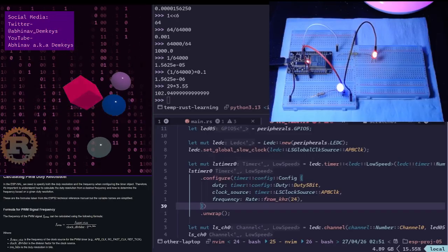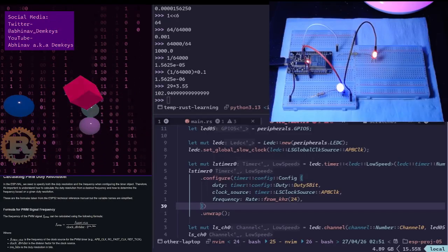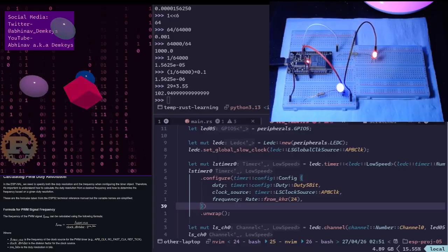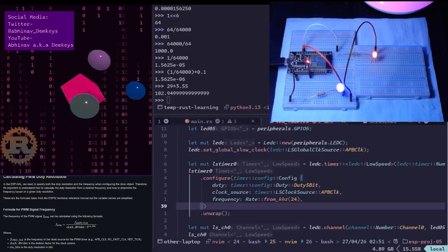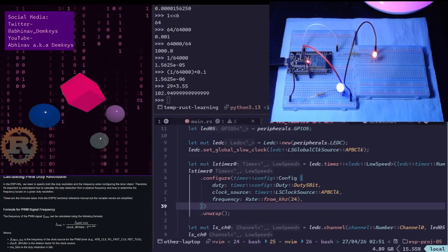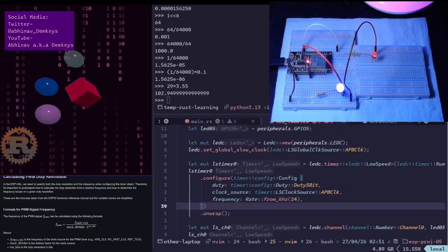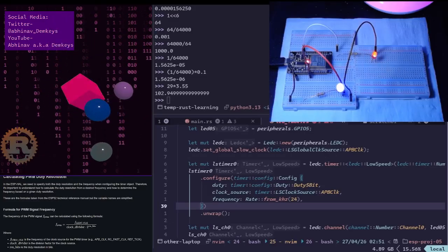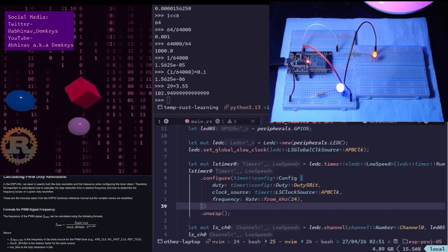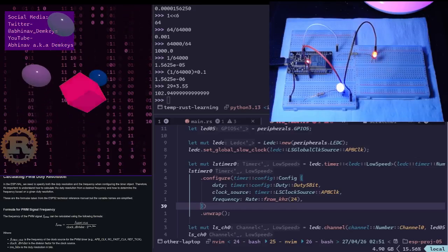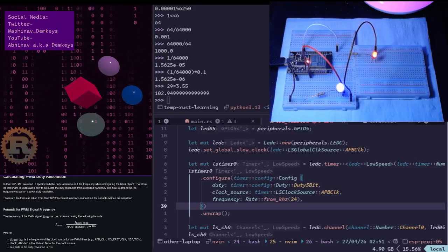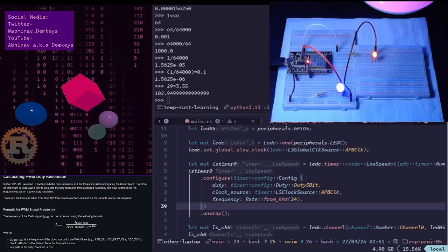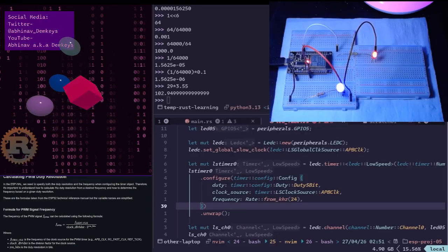Starting with the XTAL, which is our crystal oscillator, the signal goes up to the PLL, where it gets multiplied. So a 40 megahertz signal gets amped up to 320 or 480 megahertz, and from that point on, it can be sent to other places to do various things.